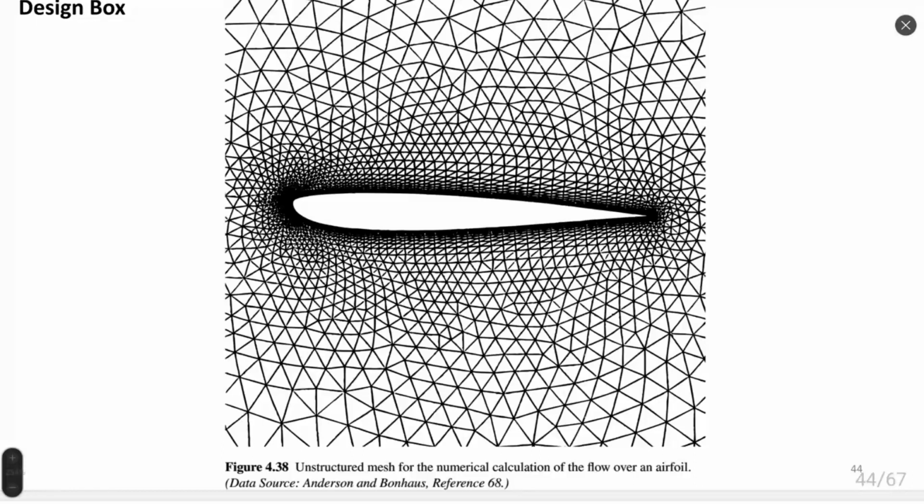What is approximation error? Is when you transform flow equations like Euler equations or Navier-Stokes equations to algebraic equation system. During this transformation, you take into account properties of mesh. And when mesh is represented in triangles, especially triangles with high skewness, when angles inside these triangles are different, you increase and significantly increase the error of this transformation from differential equation to algebraic equation.